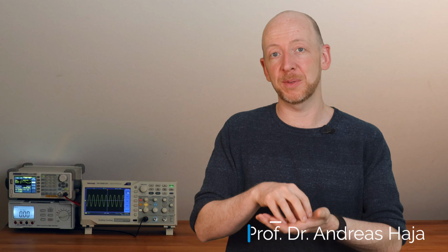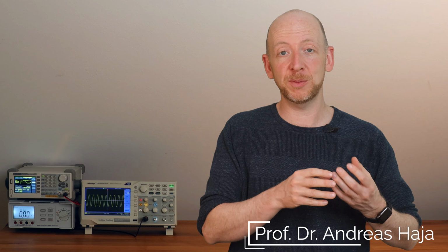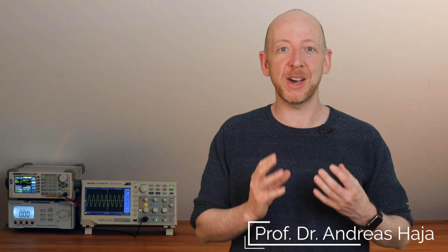Now let's take a look at the practical significance of Kirchhoff's rule. Firstly, Kirchhoff's first rule, the junction rule, can be used to calculate missing currents in a network. And secondly, from the junction rule results the formula for the parallel connection of linear resistors in a circuit. And thirdly, the junction rule can be used to calculate how currents are divided at junction points depending on the resistance values within these branches to which the junction leads.